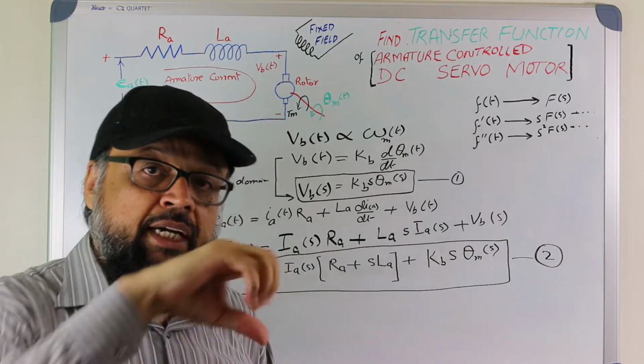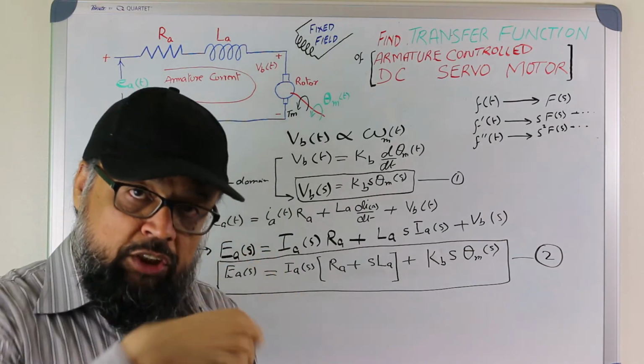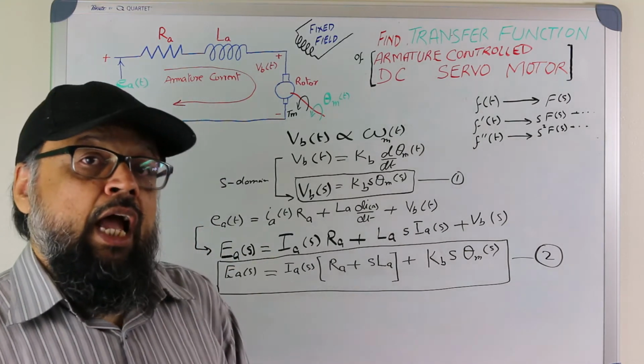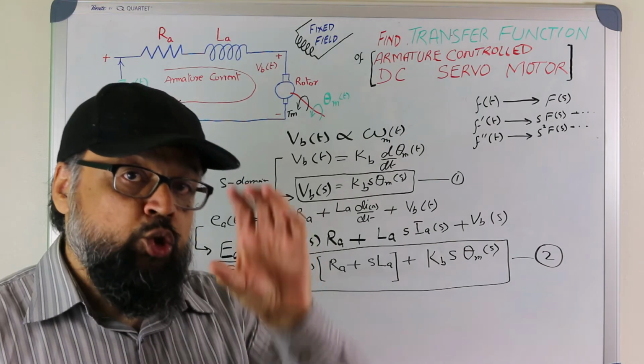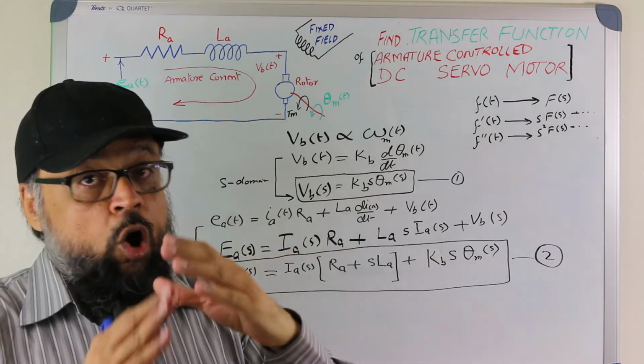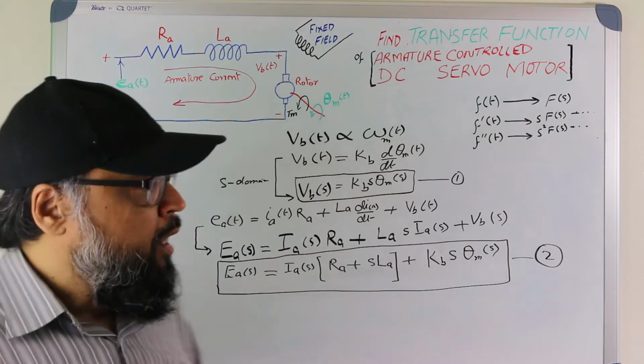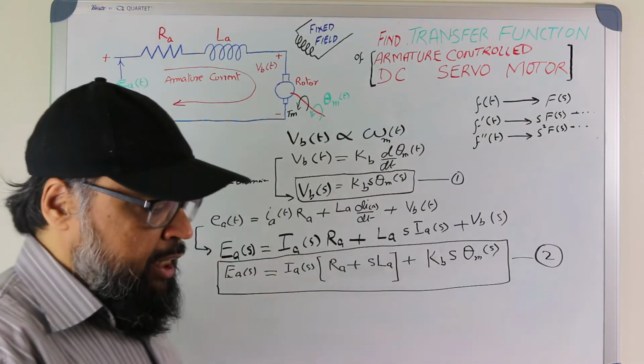Torque has to overcome the inertia, the load which we have to move, and the motor's own inertia, both factors. And the torque also has to overcome the friction, all types of friction. So we will see how we derive the fourth step, but first the third step.